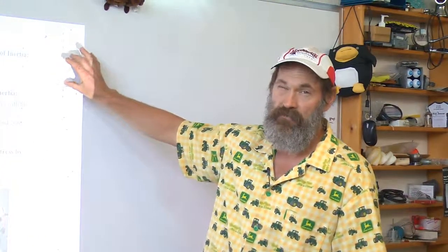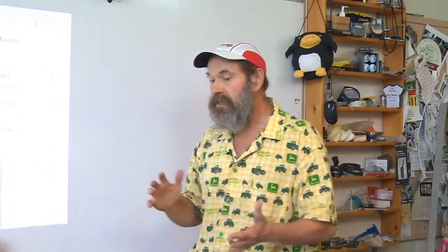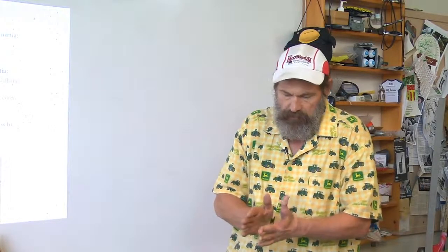Strength, not to be confused with stiffness. You can have structures that are very, very stiff, for example, a glass tube, but break very easily. Both strength and stiffness come from material that is placed far away from the neutral axis. Remember, back to topic 3, fundamental principles. And strength and stiffness in torsion both depend upon closing the section, right? Closed sections.